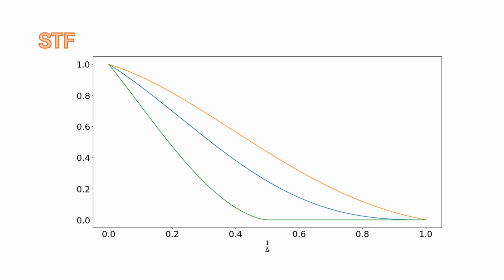So the Nyquist frequency for pixel pitch delta is 0.5 over delta. So the aliasing occurs to all frequencies to the right. Over here, this would all be aliased. If we sample at exactly the Nyquist frequency for the optical transfer function, there is no aliasing because the optical transfer function goes to 0 at the aliasing limit. If we undersample, as shown here, for these other two cases, spatial frequencies to the right over here would alias into lower spatial frequencies in the apparent image.